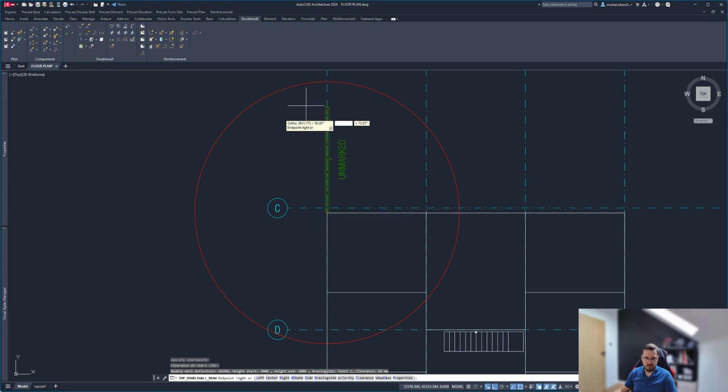So what happened here, once I zoom that out, so from the point that I clicked as the origin point of the wall, you see this large red circle. This basically gives you an immediate idea of the allowed size of the element. This is the max size of the element that you can get still within the acceptable range that's set in your project settings. So basically you can produce that, and you can lift that element out of your table or form. If we exceed that, the software won't stop us, but the element will be marked red, meaning it's too big and needs to be split at a later date.